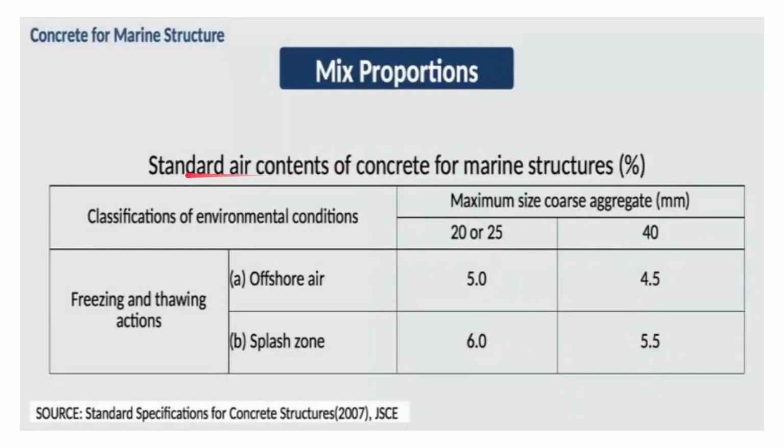Okay, so similarly there are standard air contents for concrete in marine structures. For offshore it is 5% for 20 to 25 mm coarse aggregate, and 4.5% for 40 mm coarse aggregate. Similarly, in the splash zone it is 6% and 5.5% respectively.